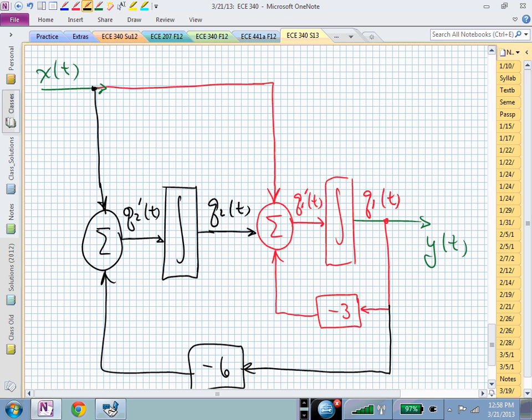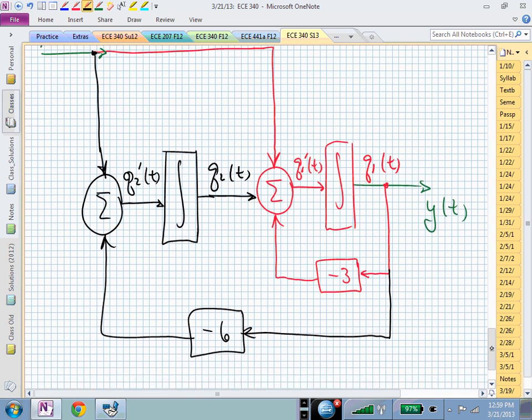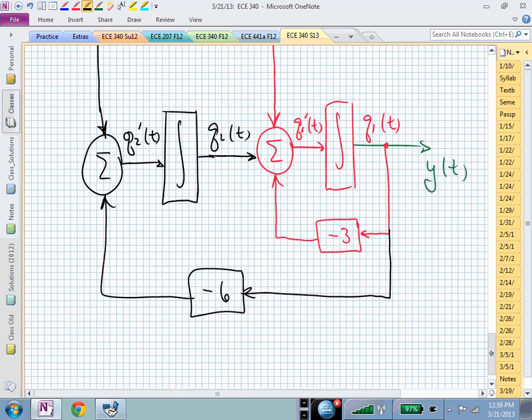And you might have an unstable system and you want to stabilize it. That's okay. You can create this block diagram of an unstable system. Now you just have to figure out, how do I stabilize it? And that would be by introducing some additional feedback paths in this block diagram. But now that we have this block diagram labeled, maybe I didn't say the fifth step.